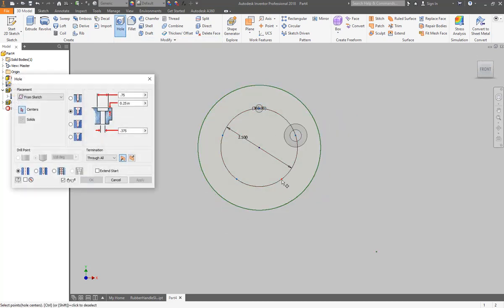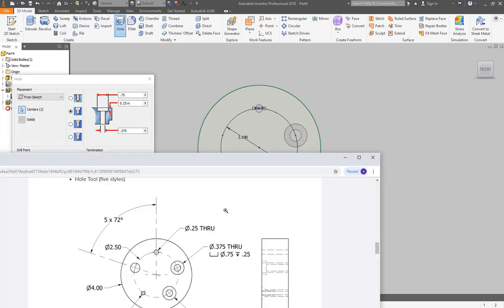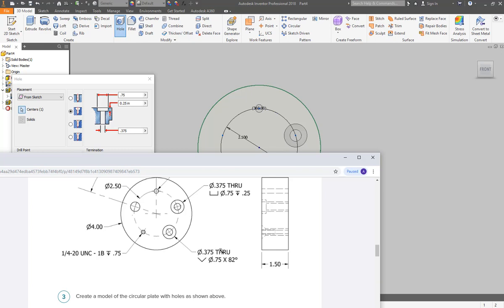Hole tool again. We're going to choose on the third. And on this one, we are making a countersunk. Now, countersunk is for a wood screw. This is a screw that the head has an angled V shape on the bottom of it. I'll show you some of these next class. And again, we've got two different size holes. This one also has an angle.